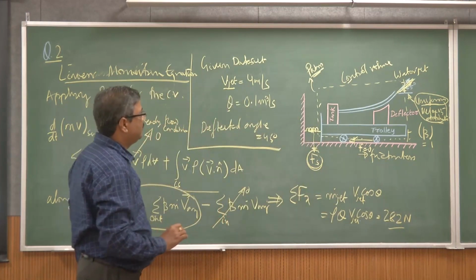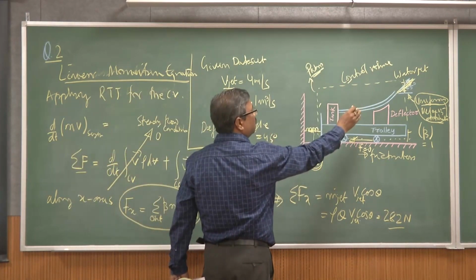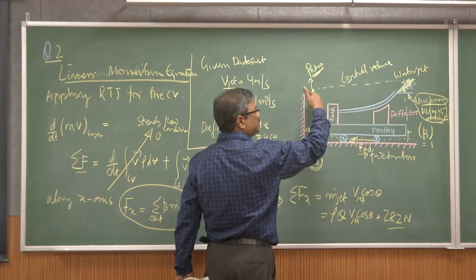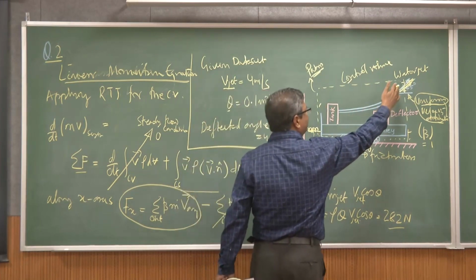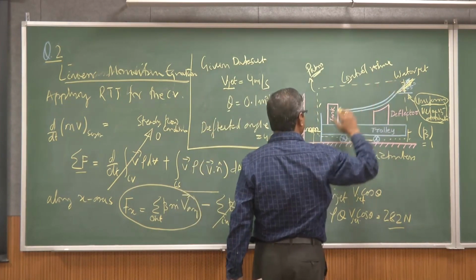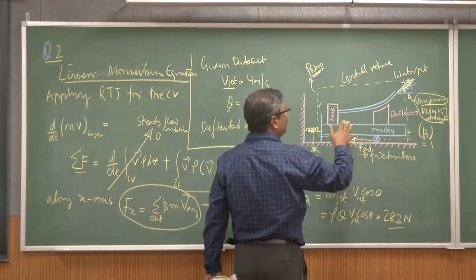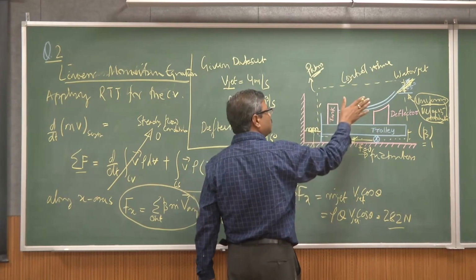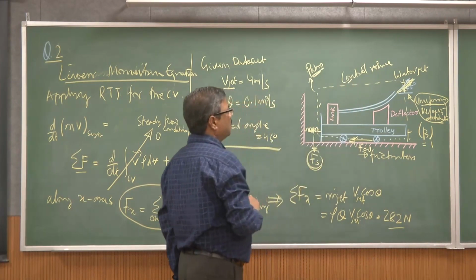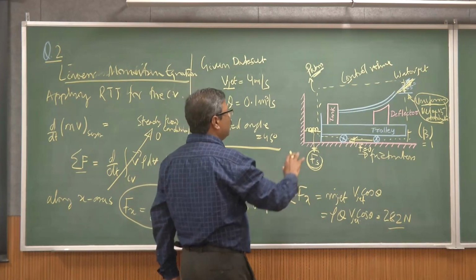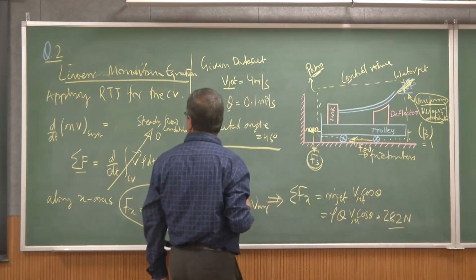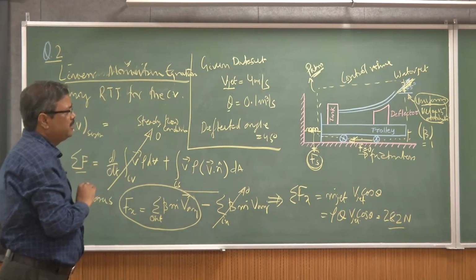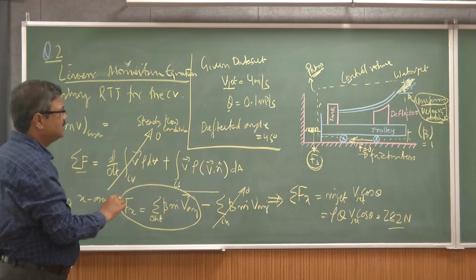Let me highlight that first you draw the control volume. Once you draw the control volume, try to find out what could be the pressure distribution, whether we can neglect the pressure difference at the water jet part, and then you look at what the mass influx and outflux are, or the momentum flux going in or coming out of the control surface. Once you conceptualize that, then you apply. In this case, we just apply the linear momentum equation because the mass conservation equation is not required.